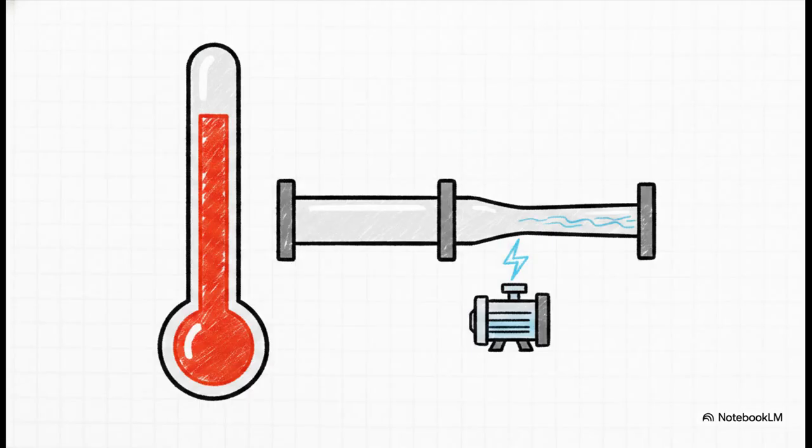In this specific design, the coils are built from the ground up to operate with a larger 15-degree temperature difference, or delta T. We are still delivering the exact same 500 tons, but because of this upfront design decision, we're doing it using significantly less water.